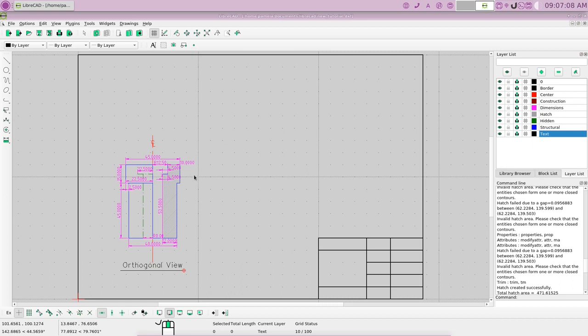Now it's difficult to see what's going on here unless we had a top view up here so that we could see the top of this unit. So we're going to draw a top view, and then we will actually be able to see what is happening in these hidden lines more clearly. Okay, so let's get ready for the top. To draw a top view, we're going to use some of the lines we have here. And to see them clearly, let's get rid of some of these things like the dimensions by turning them off. Just go to the little eye here and turn off the dimensions.